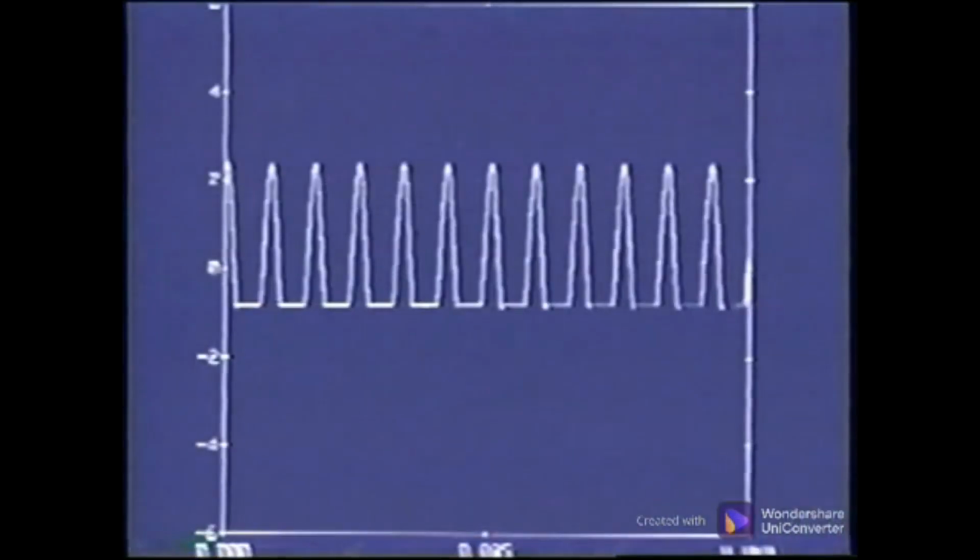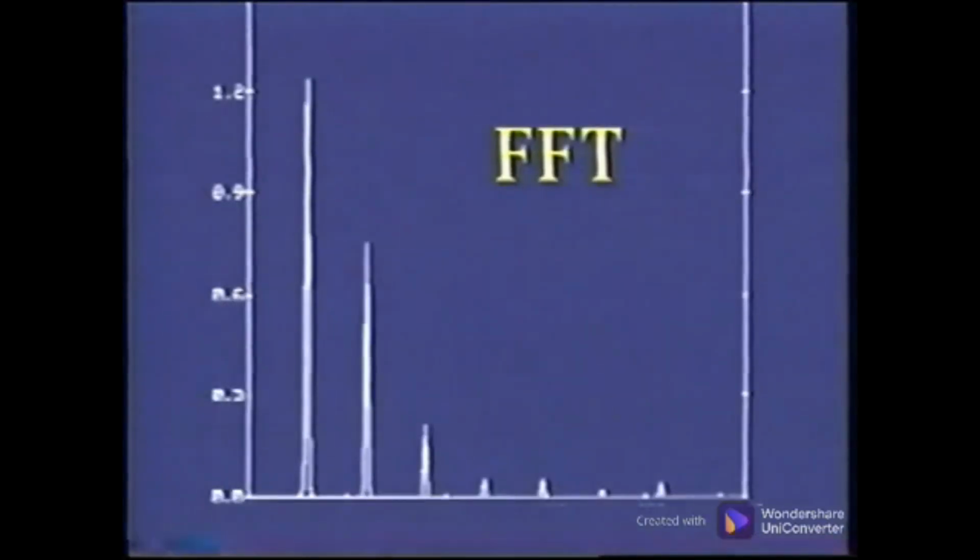Another example of asymmetry involves a severe truncation due to a restriction of motion. This waveform data is from an unbalanced condition of a spindle that is mounted so that it moves easier in one direction than the other. Again, the restriction causes a clipped waveform that is no longer a pure sine wave at a discrete frequency. The FFT process adds the series of sine waves, which are the exact multiples of the signal generated from the turning speed. The resulting spectrum has turning speed harmonics.